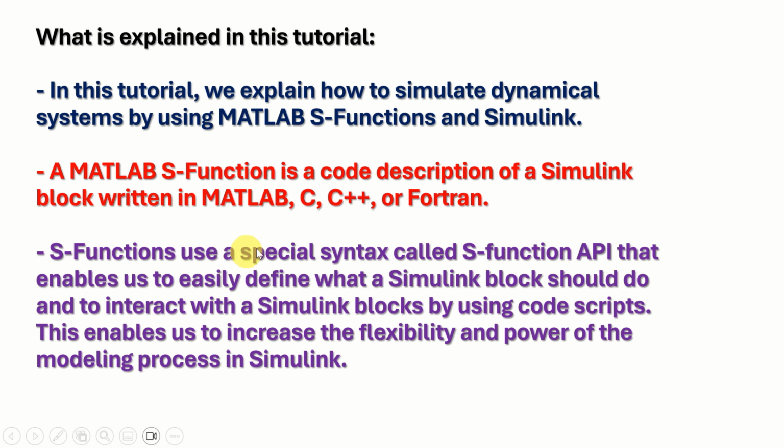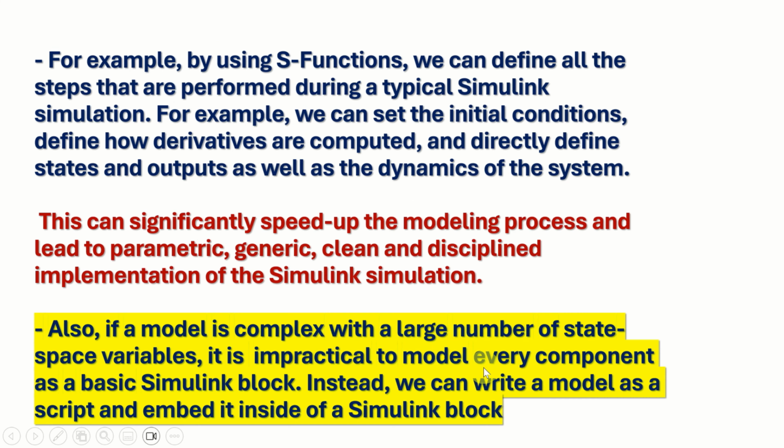A MATLAB S-function is a code description of a Simulink block written in MATLAB, C, C++, or Fortran. S-functions use a special syntax called S-Function API that enables us to easily define what a Simulink block should do and to interact with the Simulink blocks by using code scripts. This enables us to increase the flexibility and power of the modeling process in Simulink.